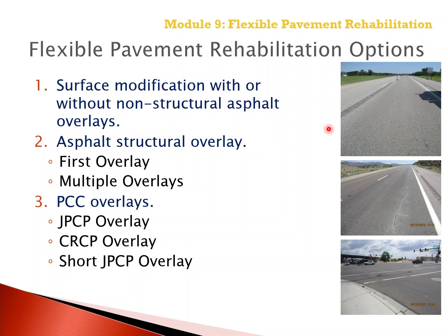The reason for the flexible pavement being rehabilitated could be related to localized areas exhibiting distress or other non-structural distresses observed at the surface that have an impact more on the functional performance rather than the structural performance. These could include raveling at the surface, bleeding and flushing of the asphalt in the wearing surface, and other surface-related distresses that do not affect the structural condition of the flexible pavement.